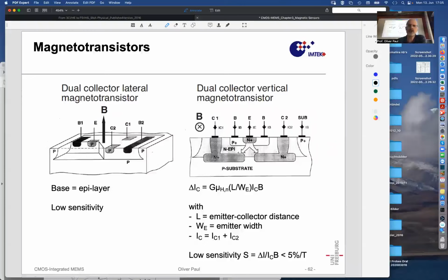So a bipolar transistor has usually an emitter, like here, and then a base, which is given by this whitish area, and then a collector, which is coming in usually only from one side towards this base and emitter pair. And then there is a contact by some buried, highly doped arsenic or antimony doped zone, which is connected to the contact out there. So we have emitter base collector.